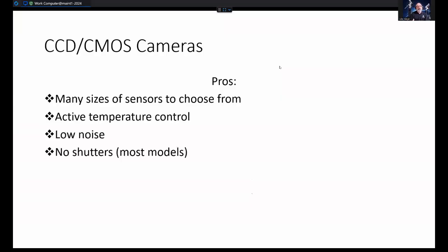So without that shutter or with a rolling shutter, your imaging chip is going to get that same gradient of light across the whole chip, uniformly illuminated. So it just makes the process a little easier of shooting flat frames. Not that shooting flat frames is difficult, but you need to understand what's going on when you're taking those frames and how it affects your calibration on your final image.